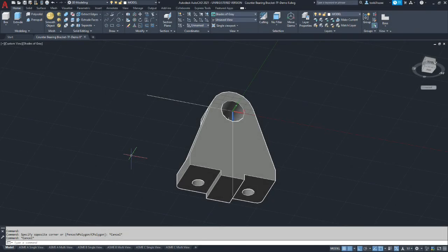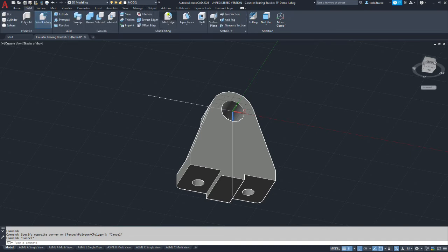Okay, so all we got left is the fillets on the back of the model. So I'm going to trace those around, and again 3mm is fine if that's what your settings are. And when you trace the back end of the part, now you could use the chain command or loop, but again I've had issues with it with more complex models. And enter, and enter, and there we go.